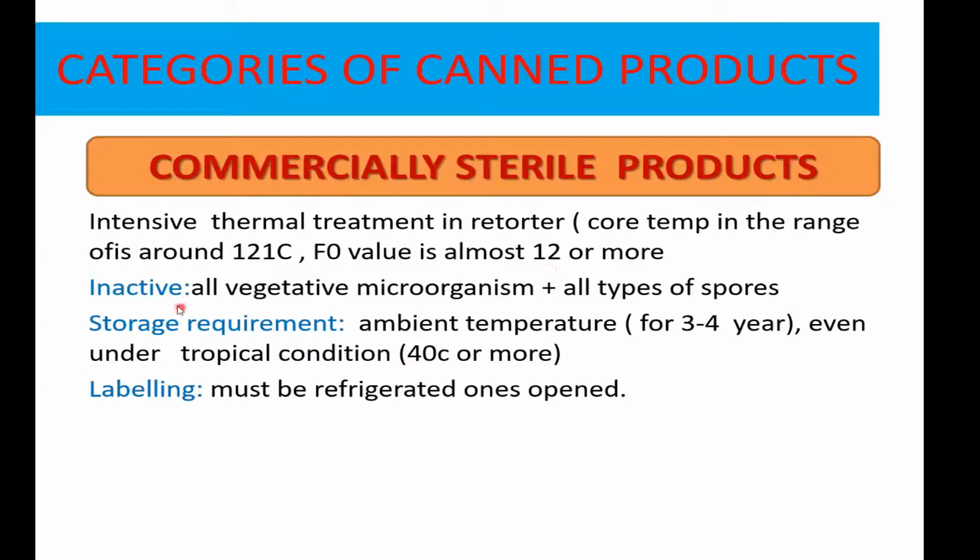So what are we inactivating in this process? We inactivate all the vegetative microorganisms, including all the spores, that is, thermophilic spores also we will be destroying. For storage, ambient temperature is fine. You can even keep it in tropical conditions above 40 degrees centigrade. You have a shelf life of around 3 to 4 years. So this is called commercially sterile products.